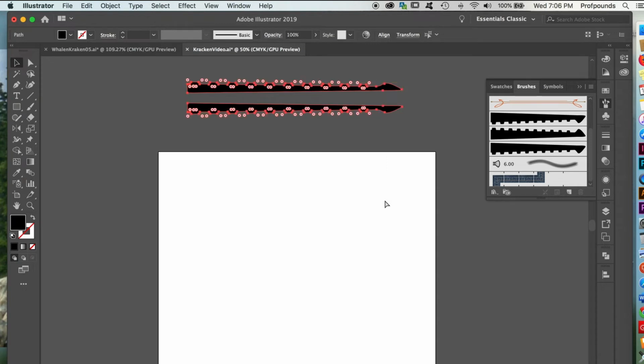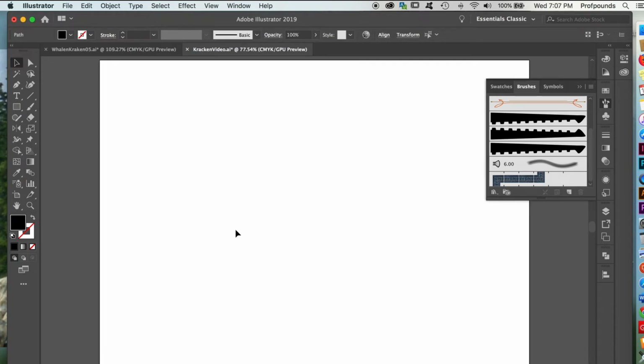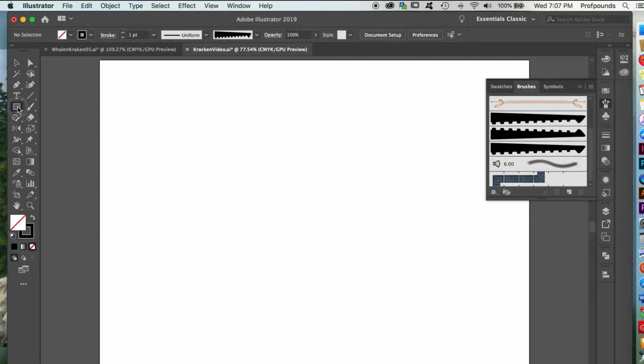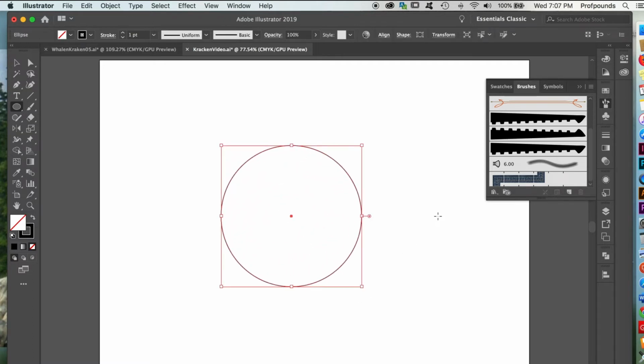And let's talk a little bit now about how to make nice smooth transitions with these. I'm drawing this line with the pen tool, which I might like or I might not. Another way to go would be to construct the line rather than draw it. I'll start with the ellipse tool rather than the pen tool. I'm holding down the Shift key as I draw to make a perfect circle. Notice these 4 control points. If I'm working with ovals and I delete sections, I can connect 2 ovals into one path, and as long as I join them at the connection points, the curve transition will always be nice and smooth.